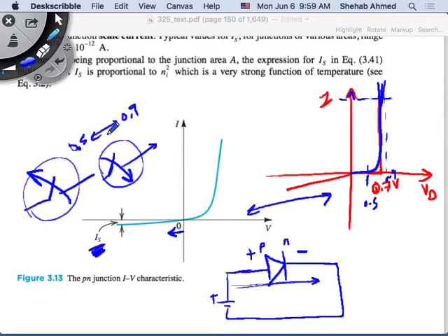So diffusion current, we said, this is like the switch closing, but is this diffusion current infinite? Can you have an infinite diffusion current? You cannot, because theoretically, according to the model that we have here, this current can go all the way to infinity. But remember, this is a physical device. This is a physical device that will burn, because now there's a power loss. Since you have current flowing, the model for this device when current is flowing looks like this.